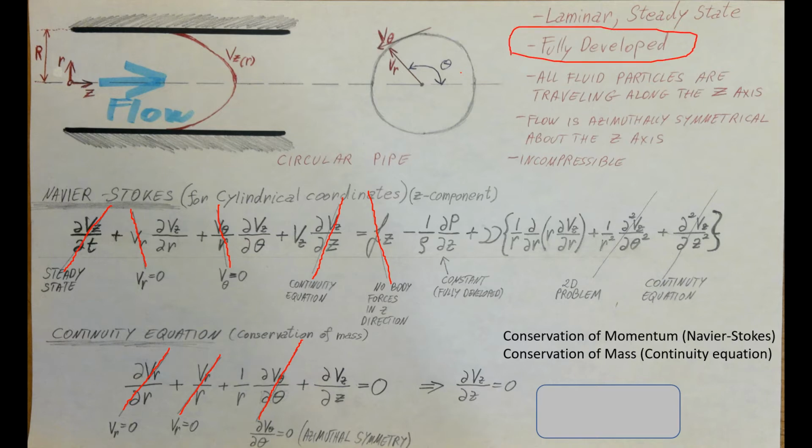That means that when it comes to the pressure term, we will have a constant component, right? The constant term. So when we end up having a differential equation after we cancel all this stuff out, it is very good that this guy will be a simple constant. If it were another differential term, then it would lead us to a partial differential equation, which would be a lot harder to solve than the ordinary differential equation that we end up with because we have this as a constant.